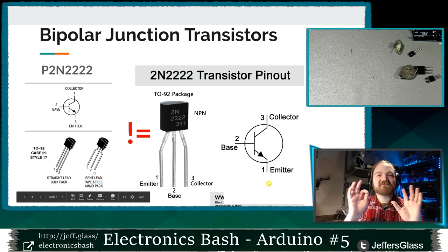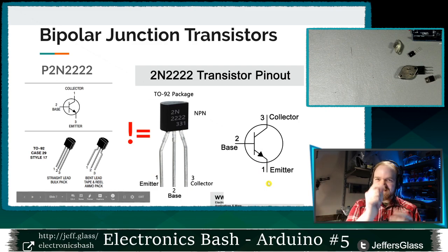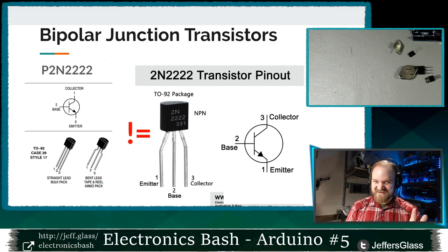All this just to say, be extra careful that you know for your exact transistor model what order your connections are in, so you're not connecting things backwards or upside down, because they, in the best case, don't work very well, and in the worst case, blow up. So you've been sufficiently warned.